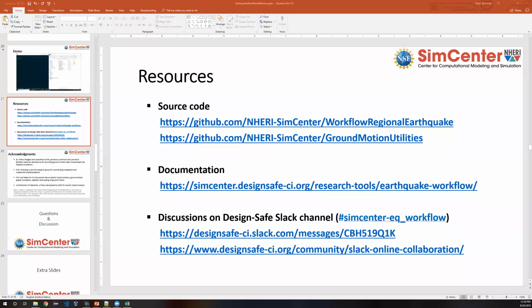Someone asked, how do you recommend visualizing simulation data? By simulation, I'm not sure if it means the OpenSees simulation, but visualizing things like the damage and loss values and the damage and loss assessment can be done in GIS applications. I'm assuming visualizing anything can be done in GIS tools, but this requires getting the building footprints and also having accurate locations of the building inventory. And we have exercised this process for the testbed and documented it.